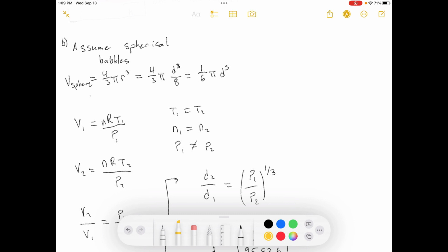Part B, by what percentage does the average bubble diameter change between the entry point and the slurry surface? Okay, so remember the bubbles going in are at 2 millimeters diameter. What size of bubble are they when they reach the top of the column? Because the pressure is changing significantly as it flows back up, because you have this column of liquid sitting over it. Again, we're going to assume that the density is uniform throughout the column and it doesn't change based off of the size of the bubbles and things like that, nor how much air is being pumped in there.